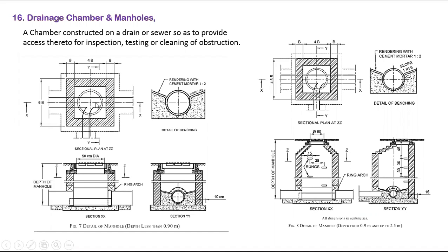That will get into the drainage. After that, it will block the system. So that's why we are not allowing particles to block in the manhole. So you should recommend circular manholes for sewage drains. In other systems like rainwater and industrial drains, you can recommend circular as well as square or rectangle, anything, no problem.